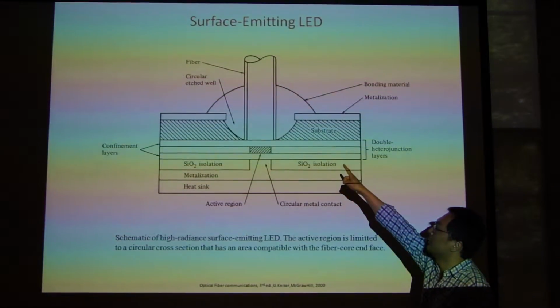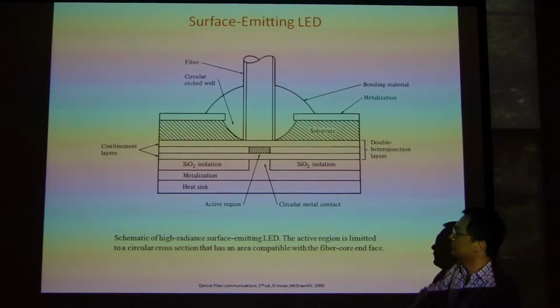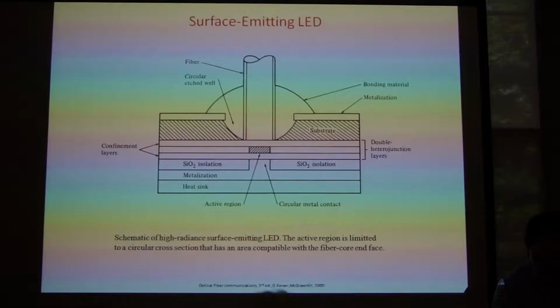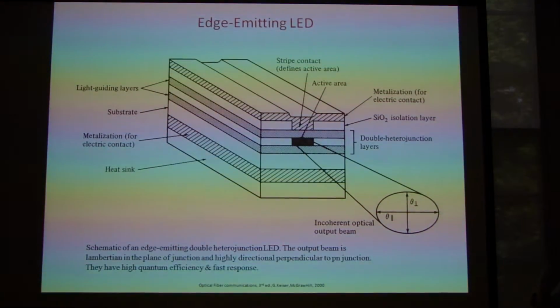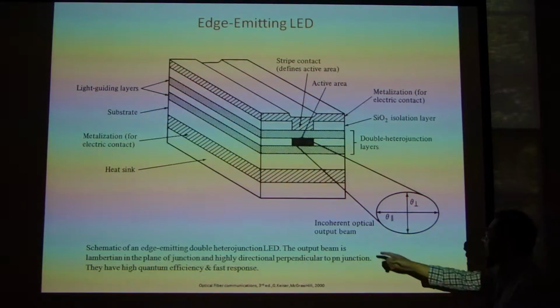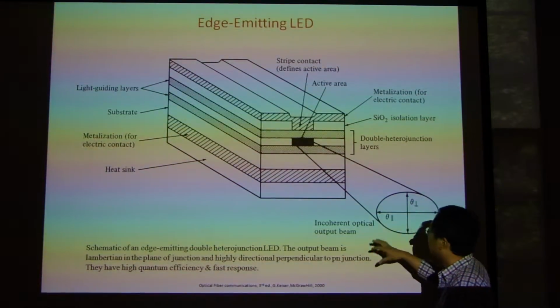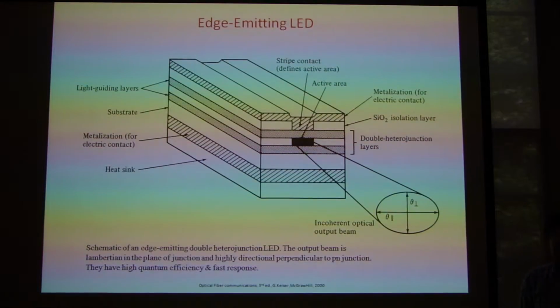Emitting, you can use the optical fiber to land the LED signal. You can also have this edge emitting. So basically, then you have to cut. You start with a 3-inch wafer, but you cut into some piece by piece. Then light can emit from the edge. That's called edge emitting. Both of them are very, very popular structures. They have different advantages, but those are two basic structures.